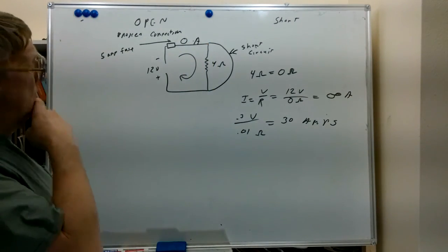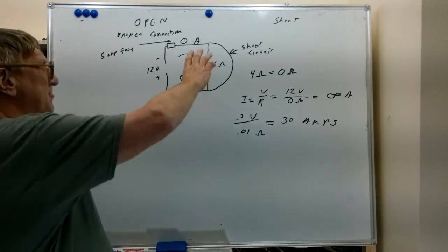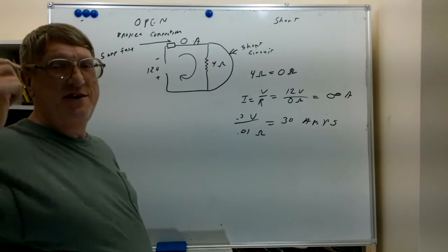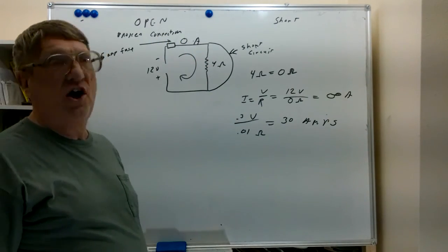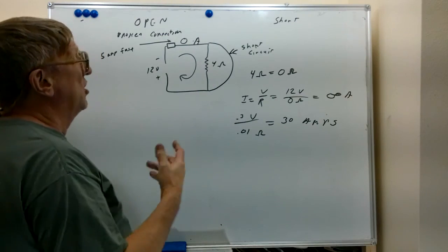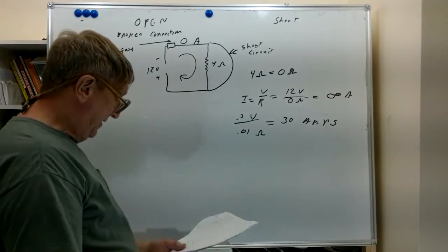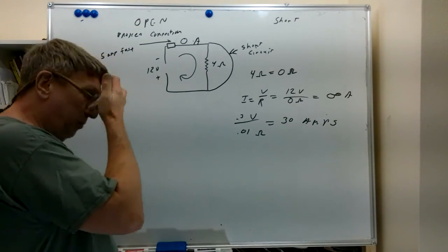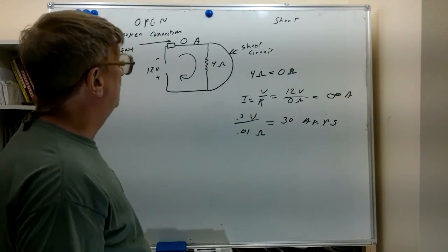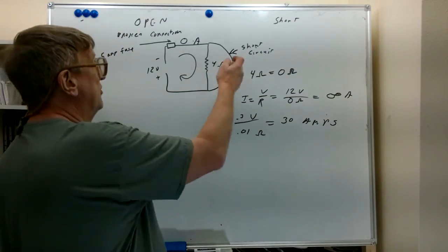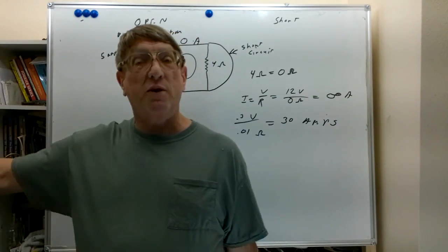So in general, resistors can increase in value or open. Now they don't usually go down because they're made of resistant materials. It's pretty hard to make it a lesser value, but some other alternate path can cause what's called a short around that thing and cause the current to go up, which is why most circuits have a fuse to protect them, and the fuse will blow, and that will be the end of your circuit operation until you get it repaired. Go in there, find the short, remove it, put in a new fuse, turn it on, see if it works. And if it ain't working, continue on.